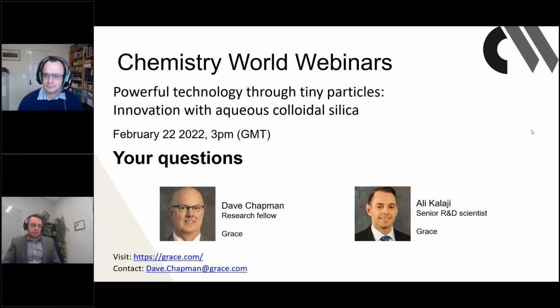The first question to ask yourself is, what is the particle size of the colloidal silica that would be suitable for this application? As you saw, we have a range of small particle sizes, 5 nanometers, 10 nanometers, up to 15. That would be the range where those kinds of particles are very useful as binders. Whereas the larger particles, such as above 20 nanometers, perhaps those colloidal silicas are more useful for surface modification. So it really depends on the application.